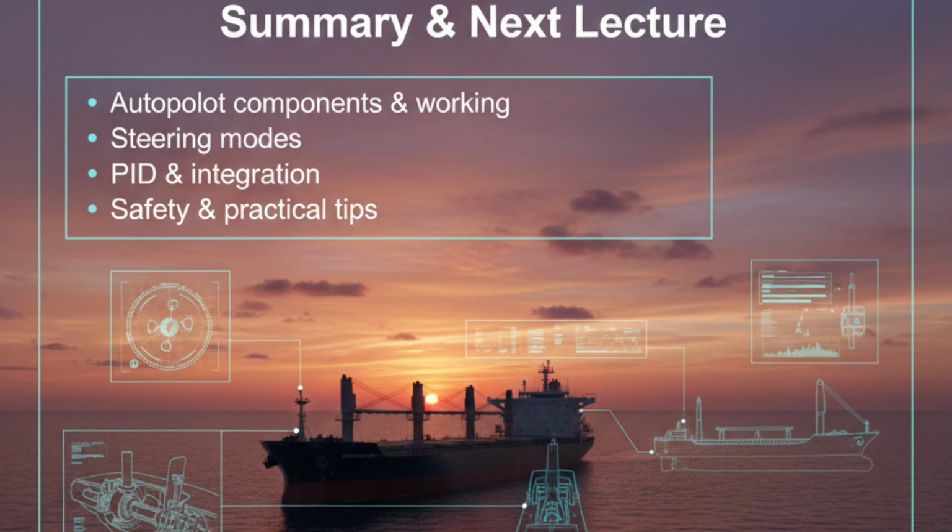We explored the PID control logic, proportional, integral, and derivative actions, and how this intelligent control system calculates precise rudder corrections to prevent overshooting and oscillation. We also learned about the importance of the rudder follow-up mechanism, which ensures that the actual rudder angle matches the commanded angle through a closed-loop feedback system.